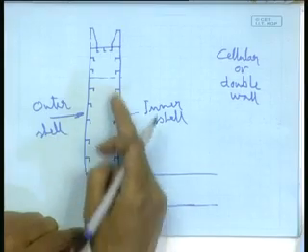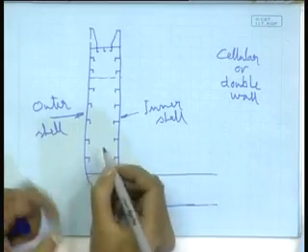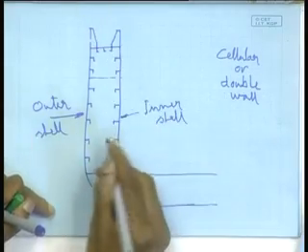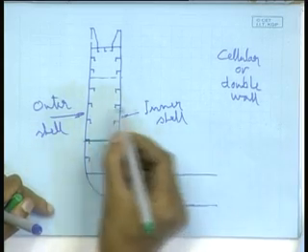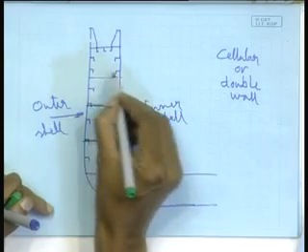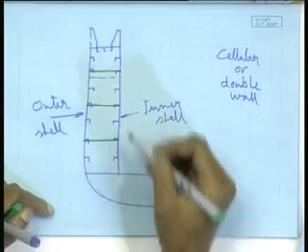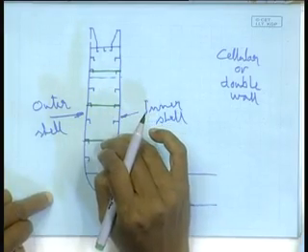You need transverses here also for the same reason, because otherwise, again the same logic, the longitudinals will have a very big span. Now, what is done here is, instead of putting all longitudinals all around, I am cutting off some pair of longitudinals by these green lines. Well, let us take this. Okay. So, these horizontal green lines that I have drawn are nothing but platforms.